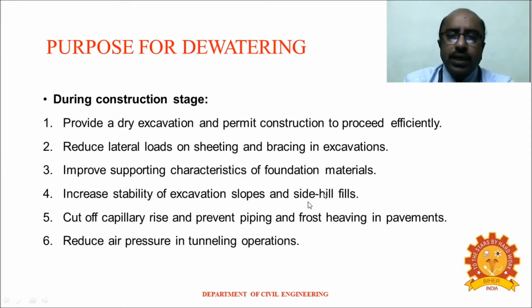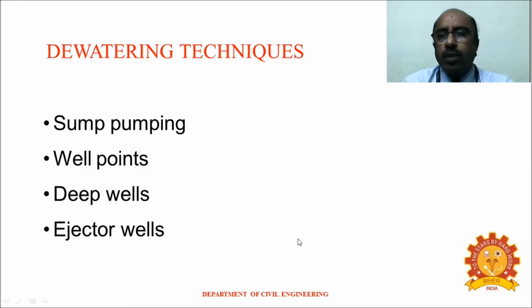In case of slopes and side hill fills, we can increase the stability of the excavation by lowering the groundwater table. Also, we can reduce or cut off the capillary rise to prevent piping and cross heaving in case of pavement. And in case of tunneling operation, we can reduce the air pressure by dewatering.